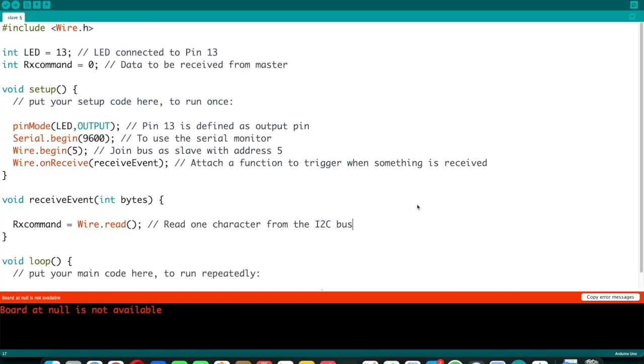Okay, so someone will tell me why here I'm reading one character which is a byte, which is 8 bits, and actually I'm transmitting bit by bit. So I transmitted a byte by the master. This byte will be divided into bits and sent bit by bit, and at the slave side, all of the bits will be rearranged again, or combined again, to form the byte.